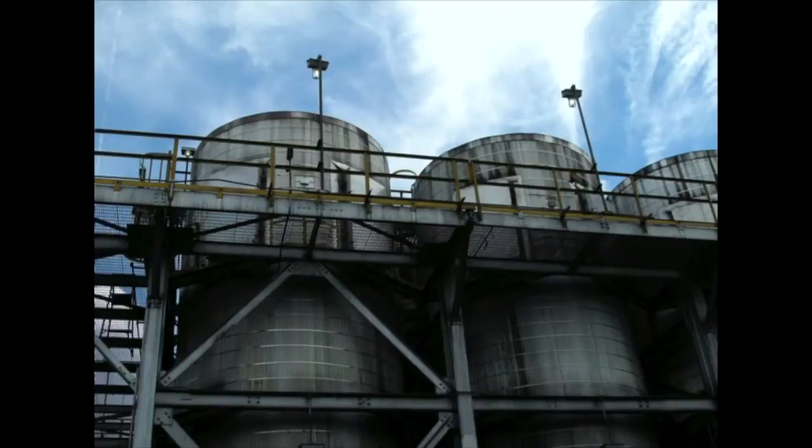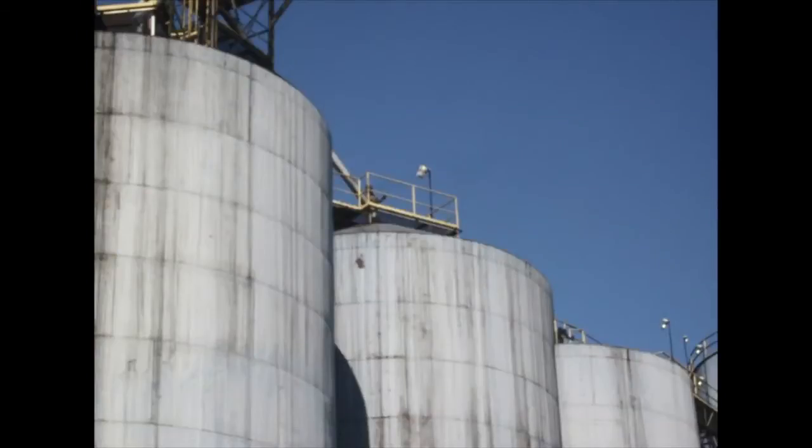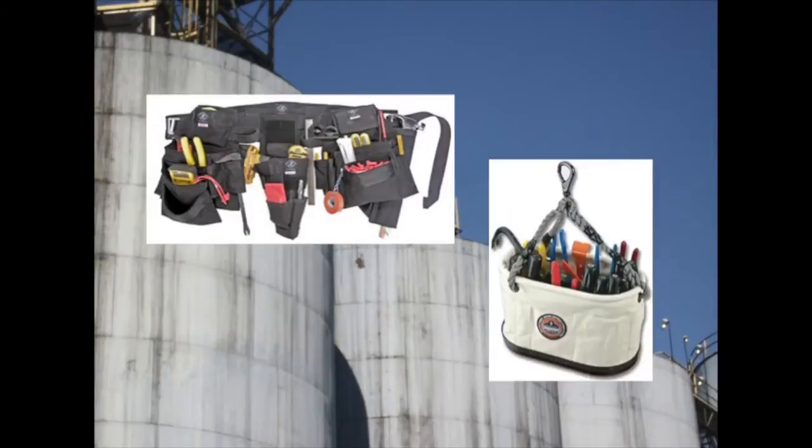On elevated walkways, including scaffolds and scissor lifts, no one is ever permitted to stand on railing or to place themselves in a position above railings without proper fall protection. When climbing ladders, platforms, or scaffolds, 3 points of contact is required at all times. That means 1 hand and 2 feet, or 2 hands and 1 foot. No exceptions. If tools or materials are needed, they must be placed in a tool belt or raised and lowered by other means.